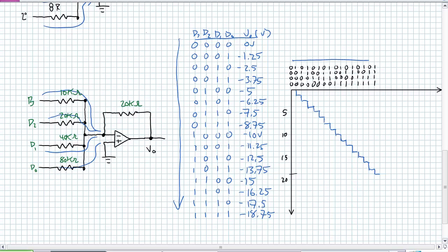And if we were to go ahead over the course of time, put in the combination, perhaps with some counter, generate quadruple 0 to quadruple 1 and a time varying waveform, what we should see is this nice, again, linear ramp. Every time we go 1 bit higher, we go to the next resolution step. If there were some problems perhaps with an offset, we could potentially see, let's say, 0 really, you're trying to represent quadruple 0, you should see 0, but you're in fact seeing -5. There might be some problem there.